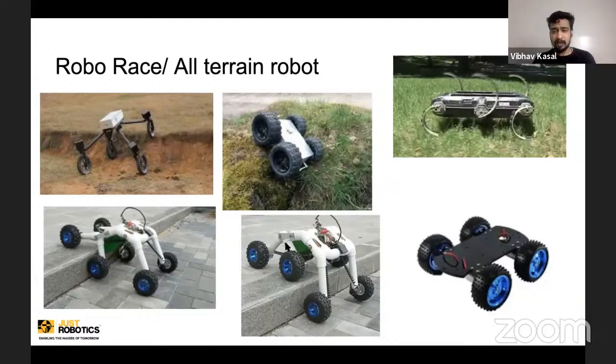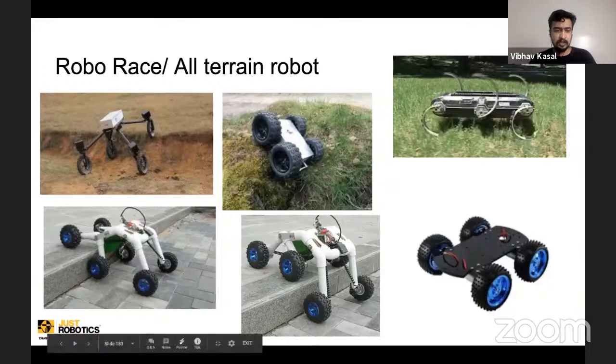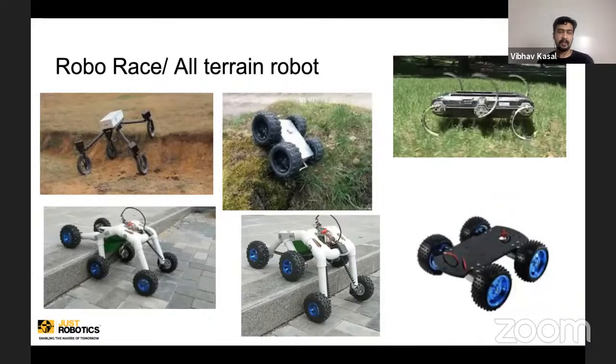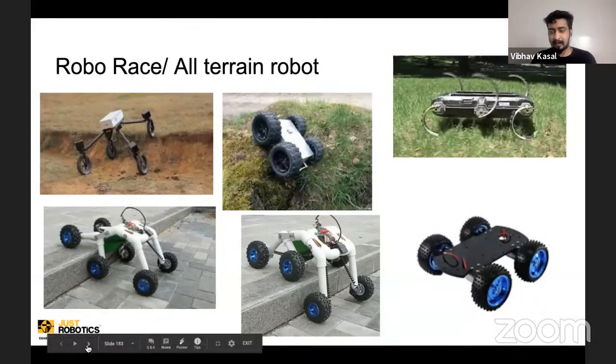In terms of RPM, if the track width or the race width is small, the faster the robot, the better advantage you will have. And obviously, students have to practice maneuverability. Having a speed control at the same time will give an added advantage in the robo race. There will be points wherein they can ride very fast, and points wherein they have to ride slow. So having a speed controller along with manual operation will have an added benefit, and we have seen how we have won competitions just by having a speed controller and having a very fast robot.